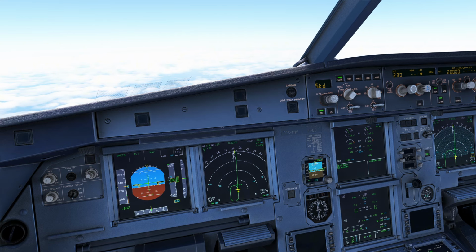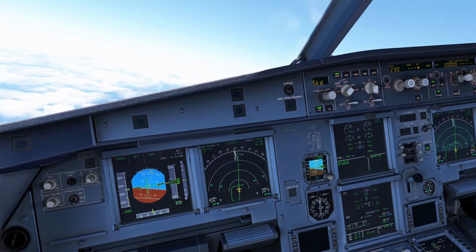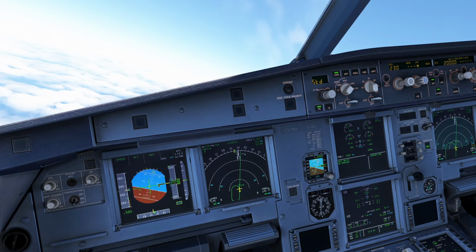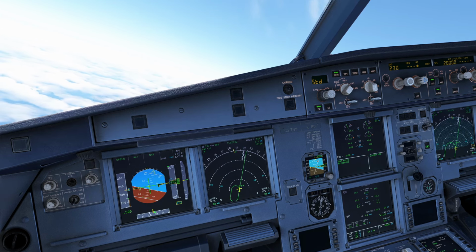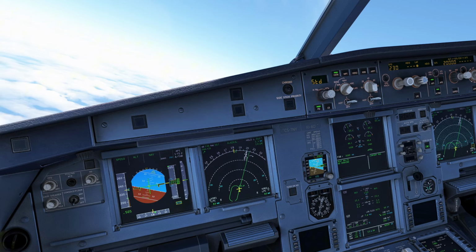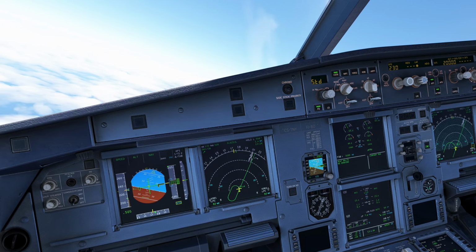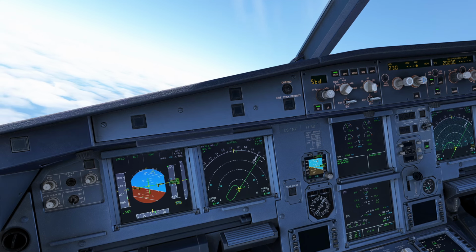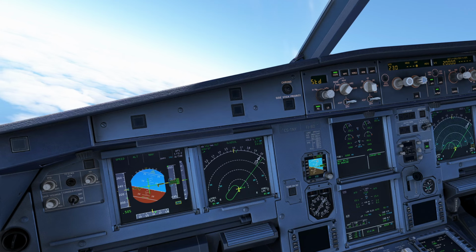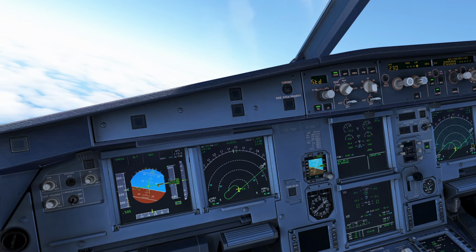Configuration changes, such as flap, slat, and gear extension, are made at calculated points, allowing the aircraft to arrive at the final approach fix or glide slope intercept point in a clean or partially configured state, then gradually configuring and slowing down to the final approach speed or VAPP by about 1000 feet AGL, or in many other airliners based on SOP will be stabilized at landing configuration and final approach speed at 1500 feet AGL.